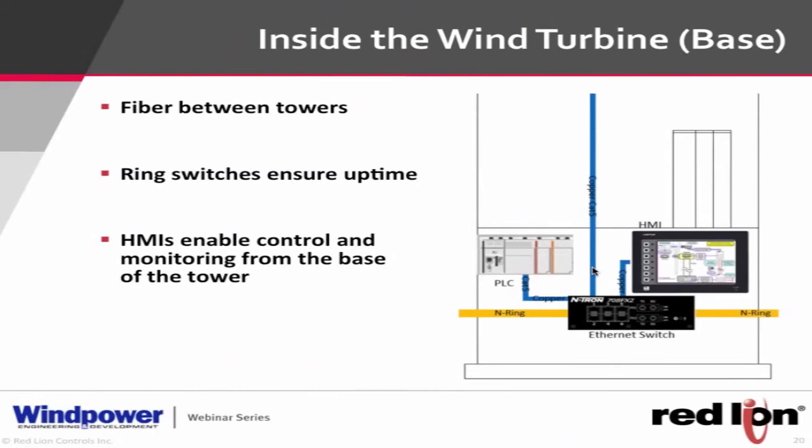happen immediately, and we need to know that these PLCs and these drives are communicating, and there's a scan time in it. We want to make sure that we don't miss that scan time. And so we need a very fast heal time on our ring, and that's what in-ring offers. And then the ring ensures uptime, because like I said, if you were to have an equipment failure or a fiber optic failure, say that someone cut the fiber in one spot, the ring itself would be healed in 30 milliseconds, which is very fast.